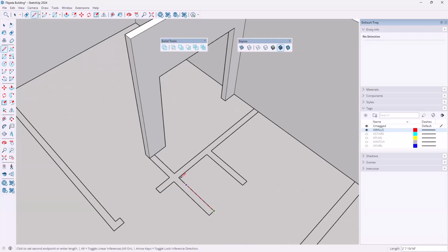And as I do this, just make sure that your AutoCAD drawing is exact or perfect, meaning that you've used the object snaps as you should have, because if not, you're going to run into some issues when it comes time to model. So be real careful with that.